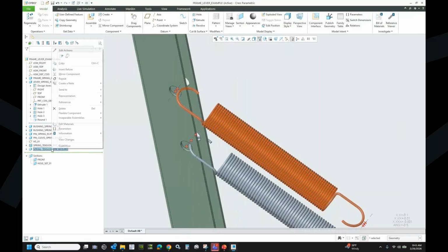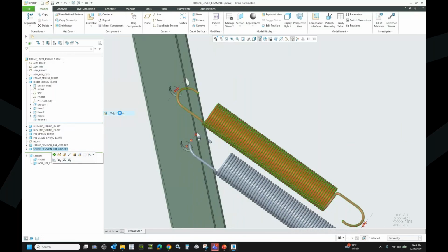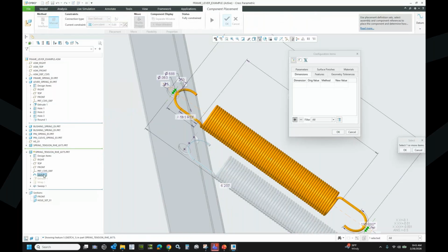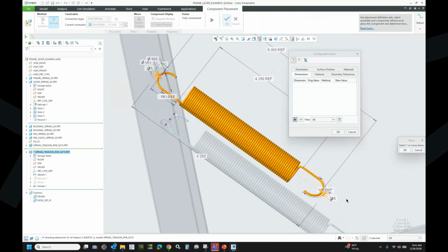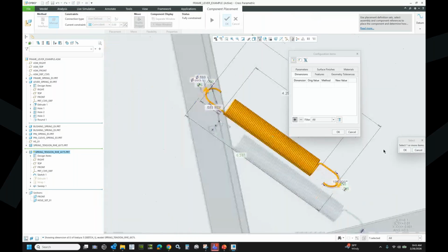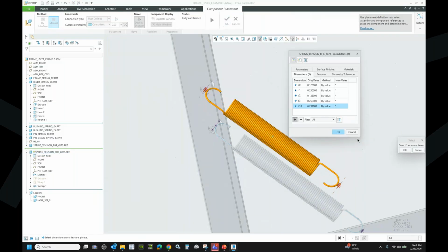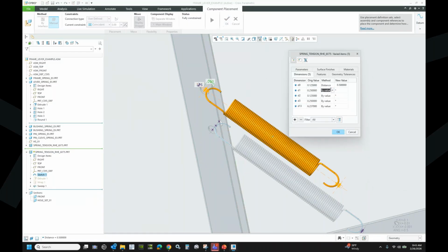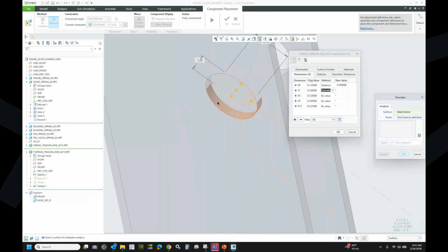So we'll go ahead and say flexible component, make flexible. Again, we're going to use the dimensions from that sketch. We'll go ahead and load all those dimensions into the buffer. And we want the one more right here. We're going to say OK, and then we're just going to set their values. So the first one is by distance, 1, 2. The next one is by diameter of the hole.